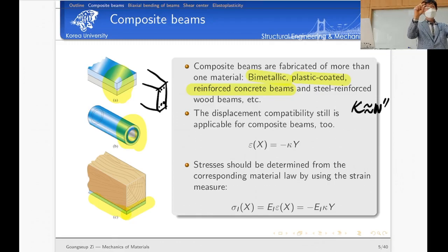So using the material law, we can connect these two. Otherwise, they are independent of each other. That's why there's no problem. So we consider kinematics without thinking about the equilibrium. Okay, forget about equilibrium. So first, I want to consider the kinematics. To describe the deformation, I want to use the curvature, and its approximation is the second derivative of deflection.